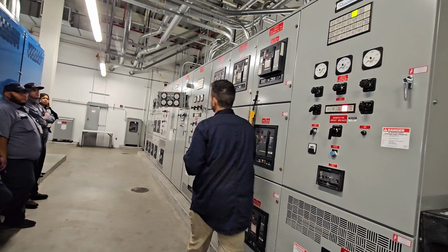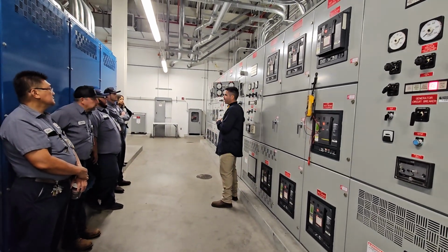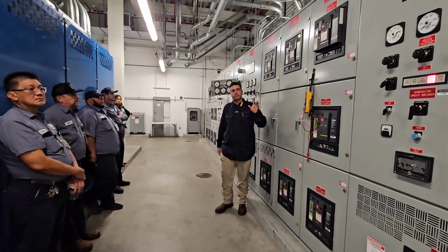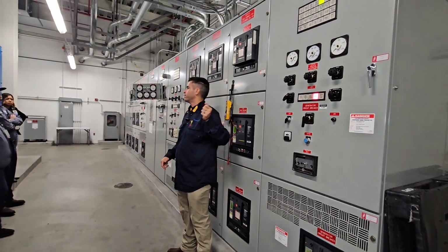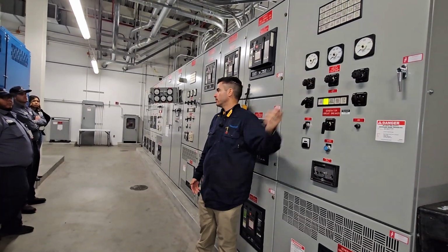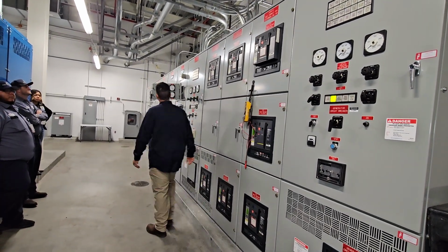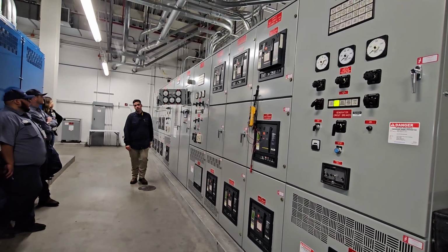You don't really need to keep this one in manual because when it loses the PLC, it's already on manual. But it's very important that you keep this in run. If these guys are not in run, you put it on auto, they will open the breaker. As soon as I turn it to auto, it opens up the breaker. Okay?